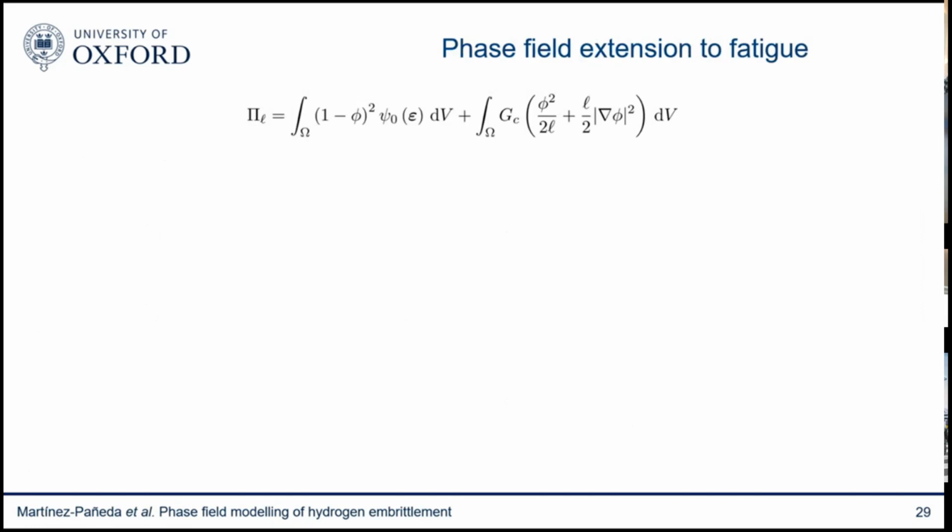Now, I think one of the potentials of phase field fracture is that we can extend it to fatigue. And of course, in practical applications, most engineering components are undergoing cyclic load. So we need to account for fatigue. And this is a challenge for many other more complicated damage models because they don't really have the mechanisms of fatigue in it.